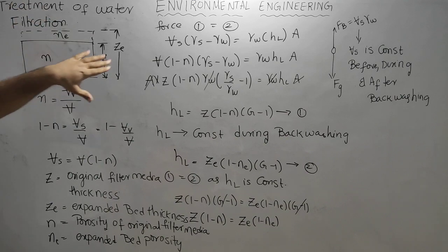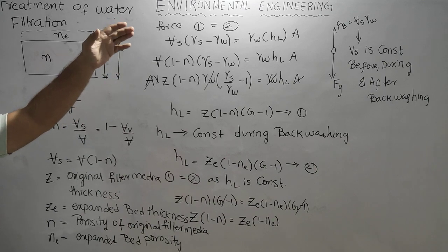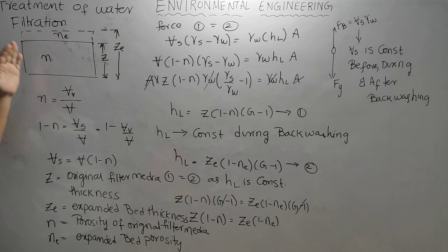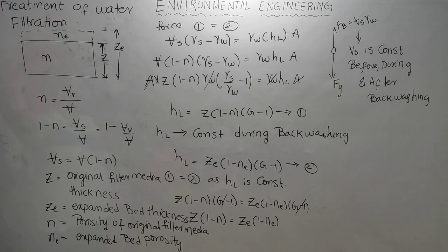Though it is not moving out due to backwashing, it will move out because of lack of support. So we are having a wash water trough up to D/2 only. If there is no support, then whatever sand is being expanded will go out because of lack of support on the lateral directions, on the sides. If there is no side wall, then it cannot stand.